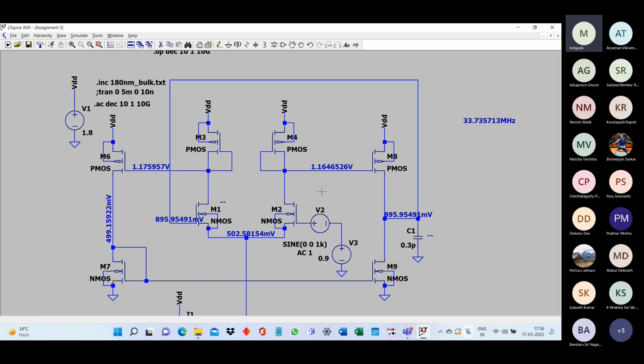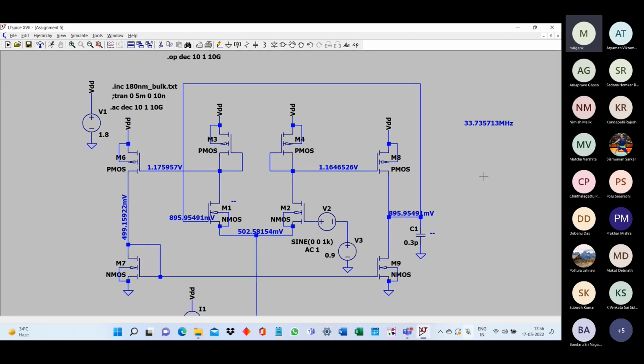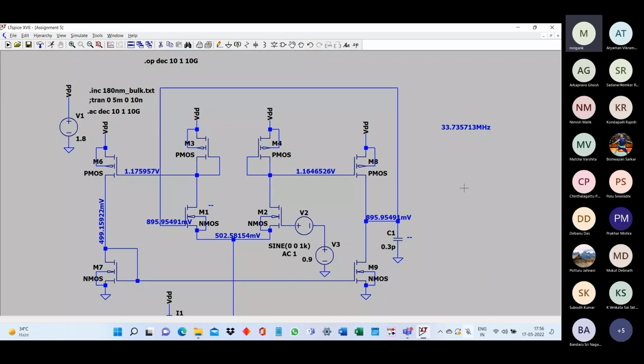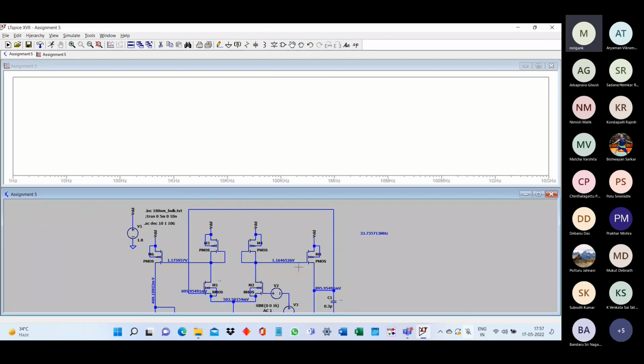But we check the phase margin in the open loop condition before connecting and make sure that after connecting, the phase margin will not be violated or the loop will not oscillate. So before connecting, we first verified that we are meeting sufficient phase margin, and after closing the loop, we will not have oscillation. So definitely, whatever capacitance we have put, it is for ensuring stable operation in the closed loop. Now you can basically look at the closed loop bandwidth.